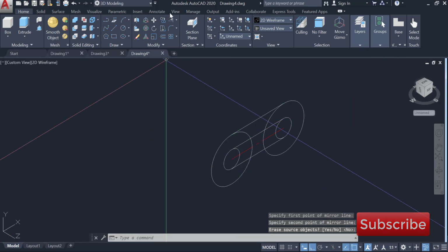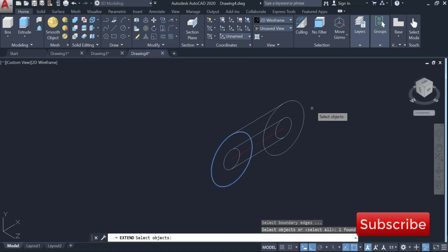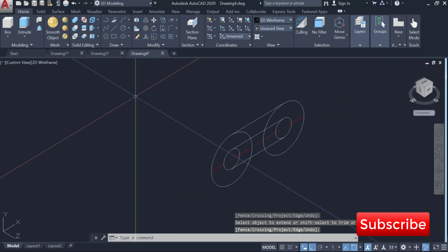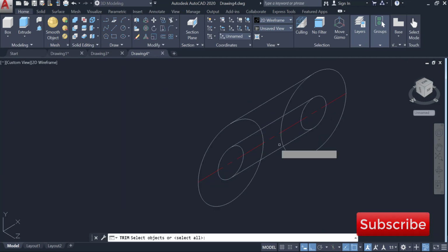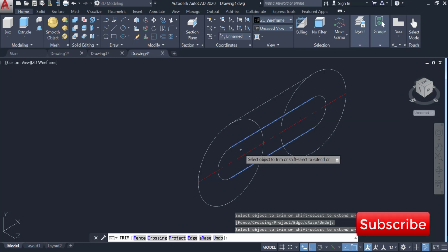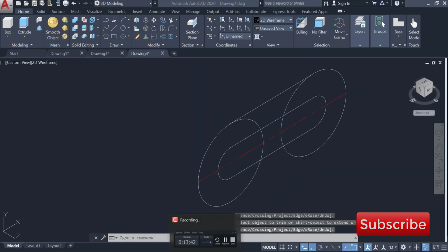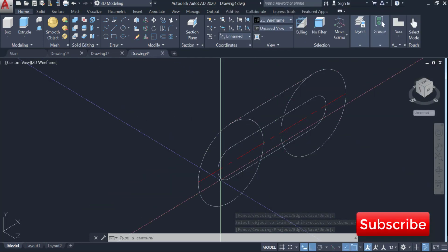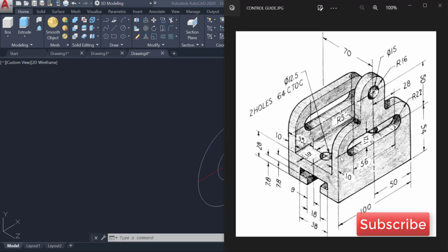Okay. I need to do some trimming. Let's extend first. So I need to extend this red line here. Enter. So the next thing we need to do is trimming. We need to select the boundary, what we are going to trim. Let's select this boundary, trim this part, because we have created the geometry already. So now we need to create only this, so we don't need the line downside.